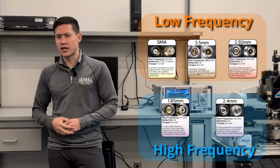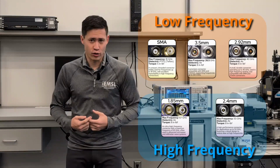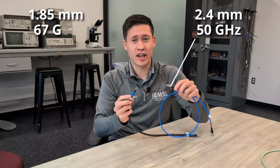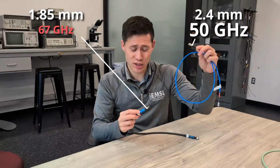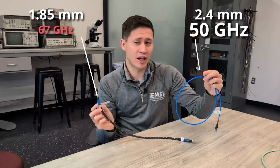However, you cannot go from a connector in the low frequency group to the high frequency group even if you have the correct genders. You'll also need to keep in mind that if you're using different connector types, the maximum frequency you'll be able to reliably measure will depend on the lowest frequency component that you're using. For example, if I connect this 2.4 millimeter cable to a 1.85 millimeter cable, the highest frequency that I can reliably measure is limited to 50 gigahertz, which is the maximum frequency of my 2.4 millimeter cable, even though I have a 1.85 millimeter cable.